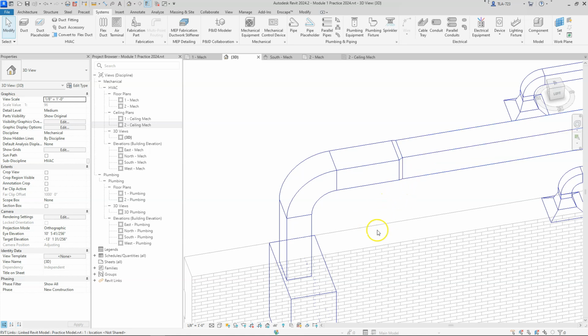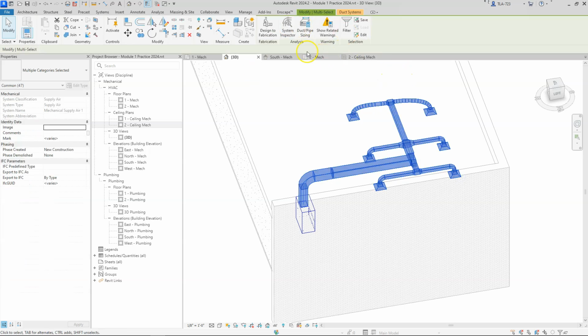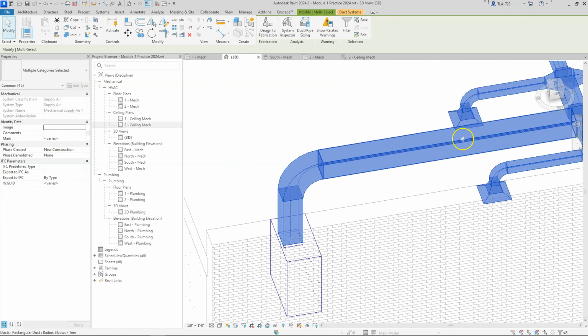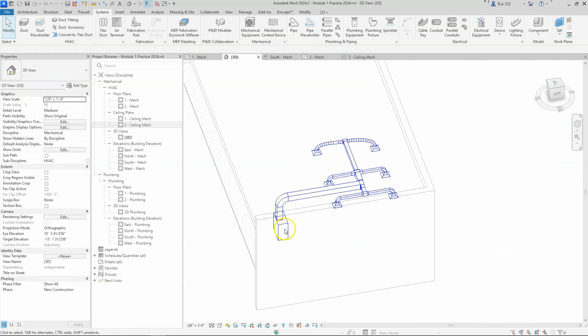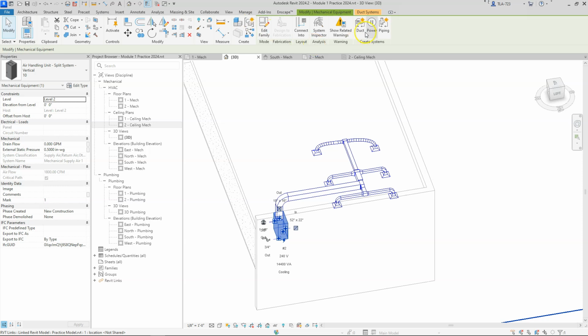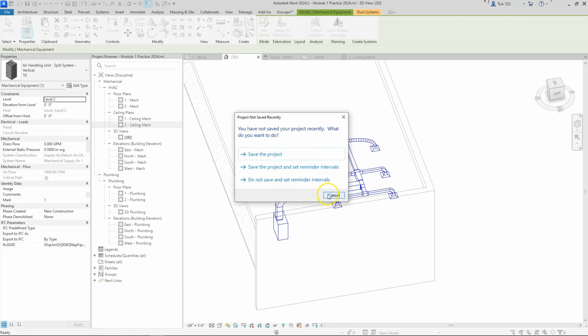But just keep in mind that at any time we can select that whole system and resize it according to the airflow that it needs. So I'm just going to do that real quick. Tab select, sizing, okay. And it changed that to where the transition happens now back at the base like before. So that Connect Into for this, because there's so many connectors, I think is why it gave us that dialog box. We have to select which system within that we wanted to connect to, and we just wanted it to be the supply air in this case.